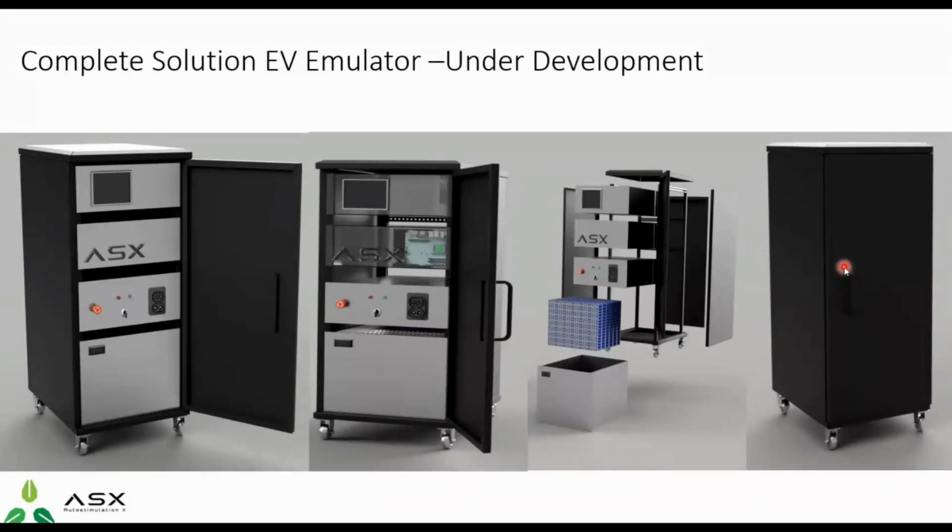It is under process right now. We are having the display for complete data gathering. It has internet, Wi-Fi, Ethernet interface, so you can grab all the data of the EV emulators. You can have the OCPP communication. You can change the CMS and all those parameters. Also the emergency shutdown, then the CCS2 connector, the battery pack, all in one unit.